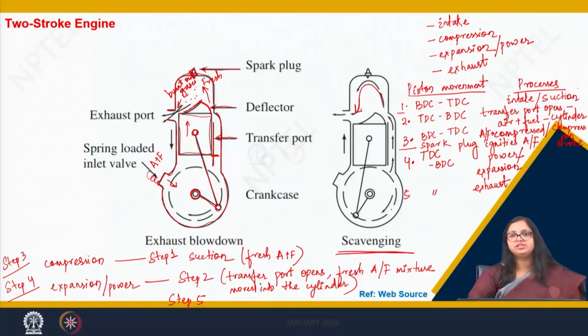Many times it also happens that this fresh air fuel mixture, if the deflector is not designed properly, may also move out of this exhaust port. So that is why the deflector plays a very important role in a two-stroke engine.